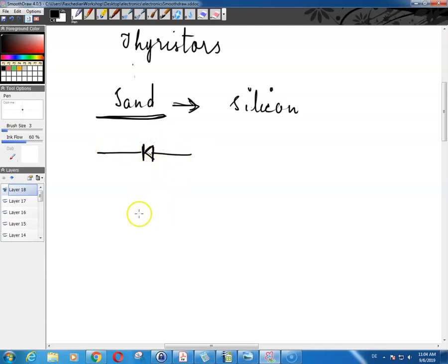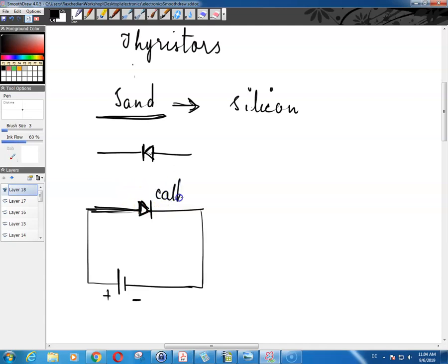the flow of electric current. For example, if you have a diode something like this, and you connect the power supply to this diode in this orientation, in diodes there are two leads. This is called the cathode, and this is called the anode. Now if you connect the anode to the positive pole of your power supply, and the cathode to the negative pole of your power supply, there will be current flowing in this circuit. Okay.